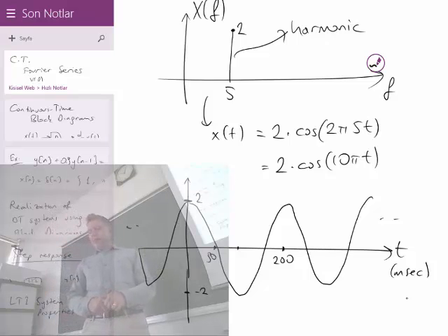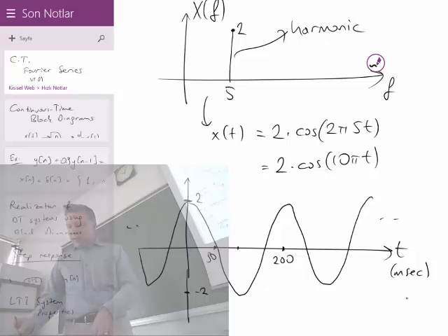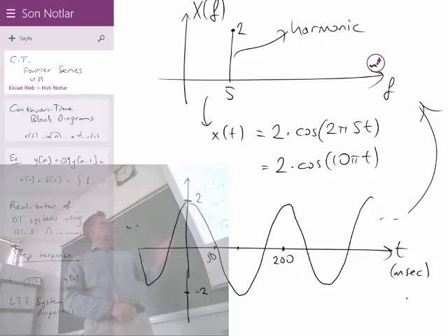So my new representation, or my new way of looking at the signal, is a transformation from here to here. Instead of drawing the cosine signal like this, I will indicate it on the frequency axis and put one sample, because it has only one harmonic. Of course, life is not as easy as this example.